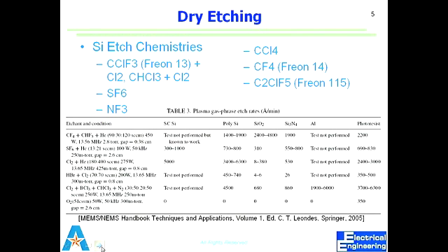Of course, the first thing is what gases we have. What recipe can we use with that equipment? Suppose we have all of these available. Now what would define my choice of recipe? The etch rate between different materials, and what do we call that?